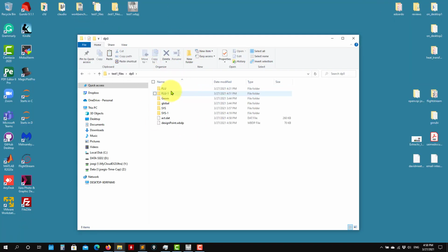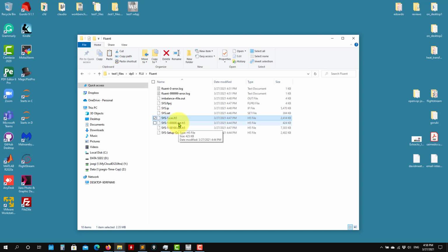So something about the Fluent files, just to make it clear. You see here that you have a case file, .cas.h5. Here you have the mesh with the case setup, and in the .dat, this is the solution. It's telling you that you have a solution now at iteration 100. So this is case setup and mesh, and this is the solution.